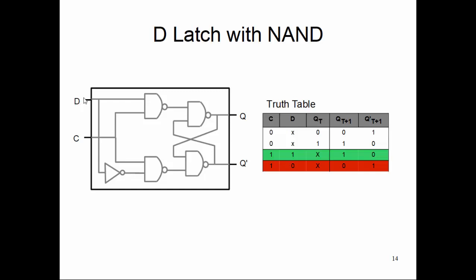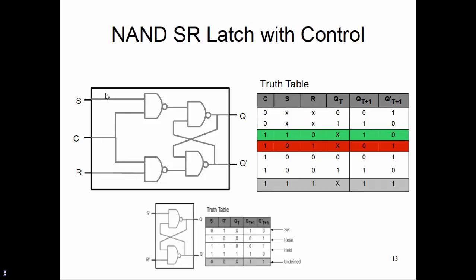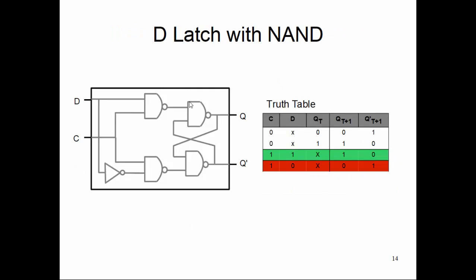The circuit using the NAND SR latch is usually a little bit more complex because it needs to make sure it does not produce a race condition. For the D latch, there is no race condition. So whoever's top-level system is using this storage with a D latch, it is simpler than a system using an SR latch. So that's one thing.